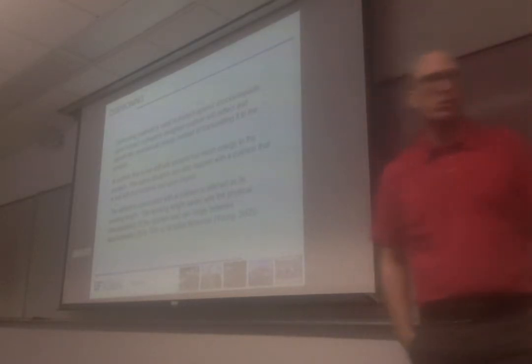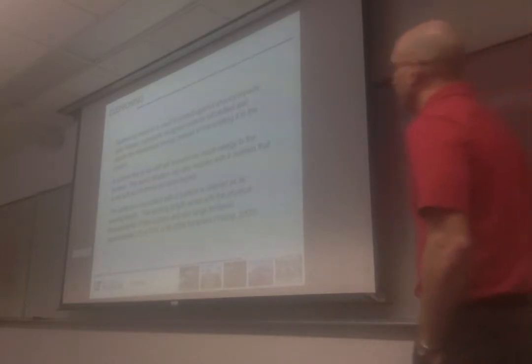So, cushioning materials, we've been talking about them for a long time, and we know that they are used to protect against shocks and impacts. We know they cause issues with vibration. We know that together the product and the cushion system have a natural frequency of their own, depending on the stiffness of the product, the stiffness of the cushion, and the mass of your product. They may cause problems because of vibration, but they're there to protect against shocks.